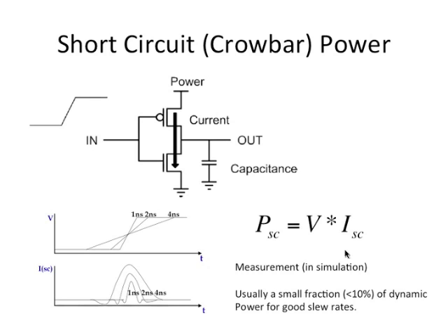And if you see that current as a function of time, the current between VDD and ground will be very small, but during the transition, when an edge happens, there will be a spike in the current and then it will go down. It will be almost the shape of a triangle. You can approximate it well with a triangle, right? The slower the ramp rate, the slew rate, the longer the duration when I am short circuiting. So if I say ISC is the average short circuit current, then the power due to short circuit is V times ISC.